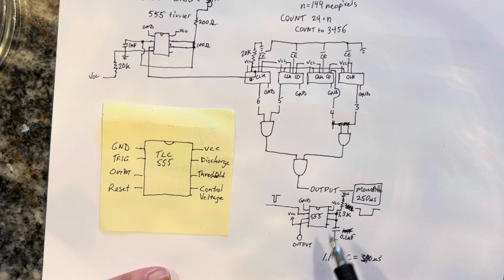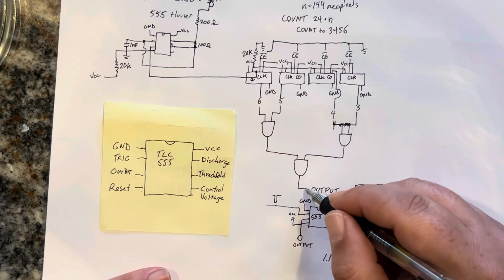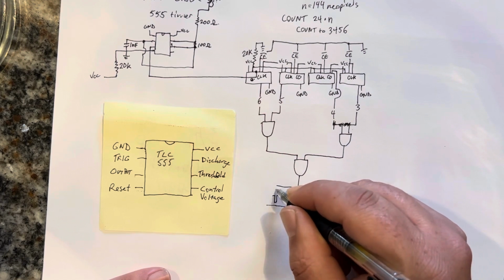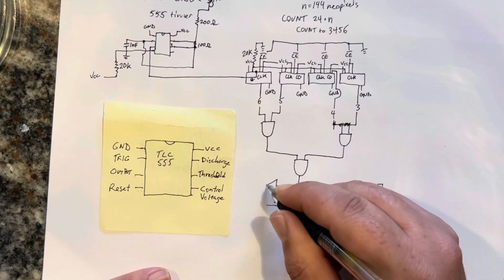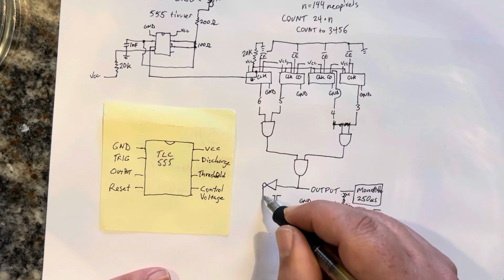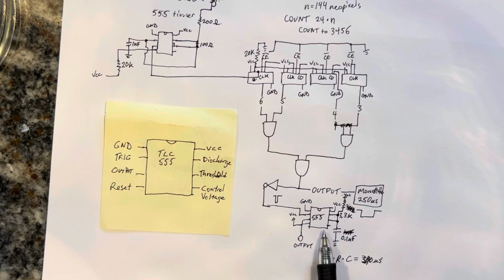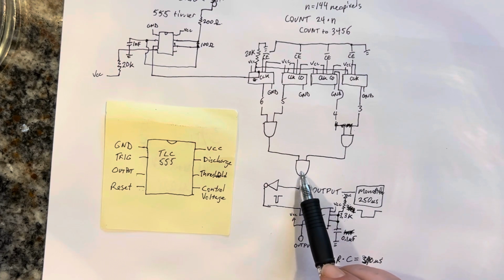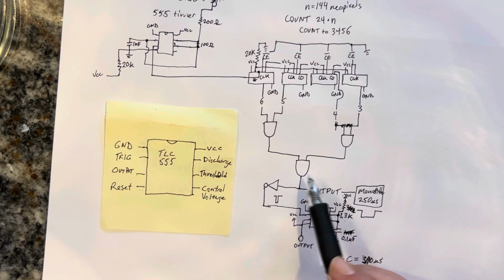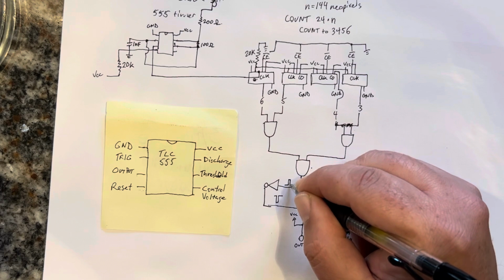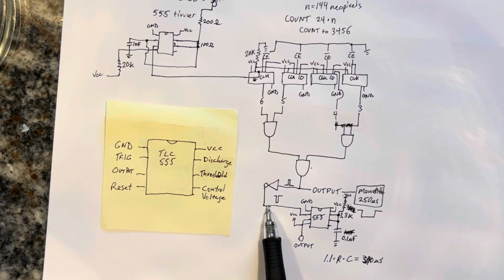And so in order to generate that output, what I did was I put it through an inverter. And that triggered the reset pulse of the 555 timer once the value of this AND gate reached 1, because this was a positive value that comes out of here. And in my case, I didn't use an inverter chip.